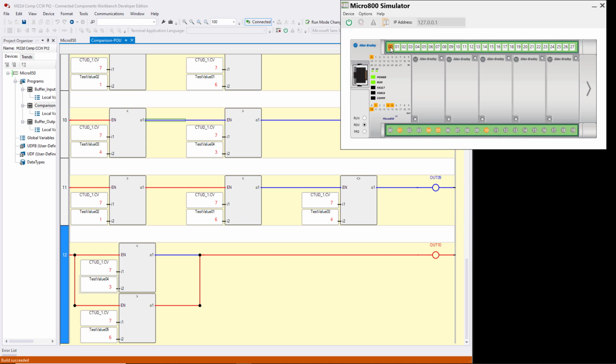If I go one more, now it's true again, and it'll be true no matter how high you count from this point. So it's a limit instruction basically that says that this rung is true outside of the limits of 2 and 7, or if you want to include the limits, it's true for 2 and below, 7 and above.